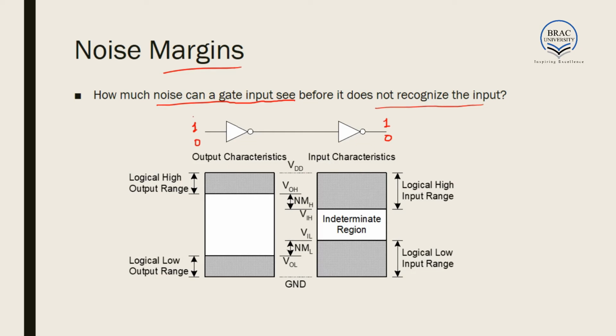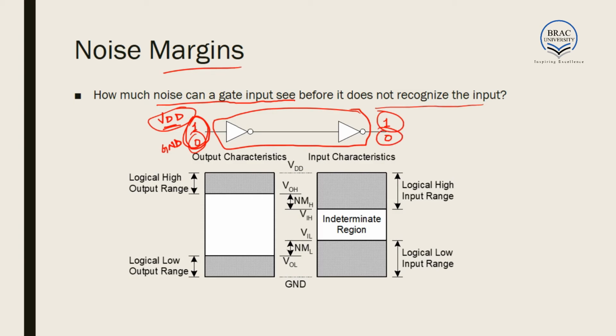So, the noise margin concerns the input values. We consider input as 1s and 0s, but actually 1s are VDD and 0s are ground. Whatever the input is, it might not be equal to VDD; the input may have fluctuations. For example, let us say VDD is 5 volts, but the input might be 4.5 volts or 4.3 volts. Will the circuit consider 4.3 volts as logical 1 and give output as 1? Or will it consider 4.3 volts as logical 0 and give output as 0? Or will it give a floating output? We don't know. In order to understand that, we have to understand noise margin.